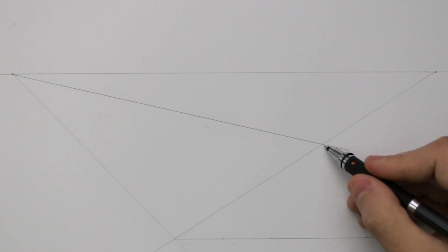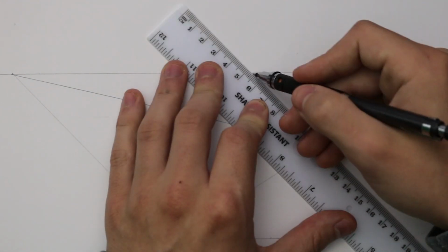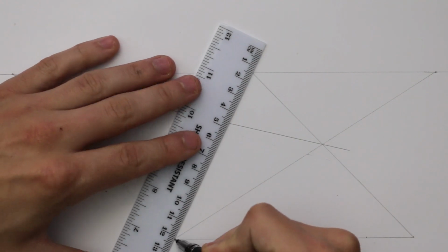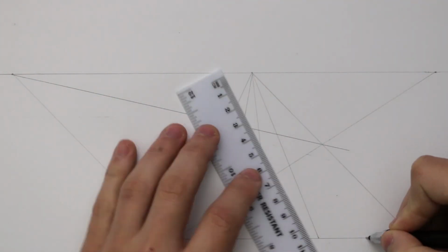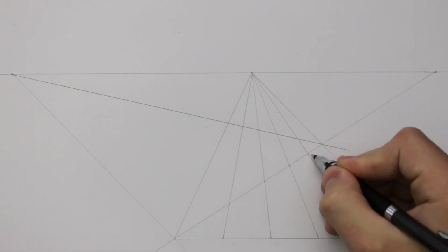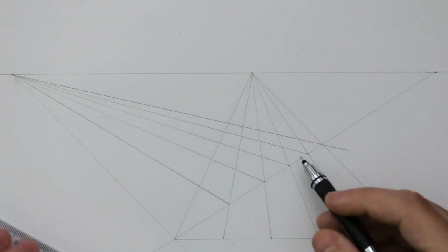And now I'm going to bring a line from the end of this parallel one which we just created to the other corner of the grid and extend it until it meets the horizon line, and that will give us a point that we can then use to divide that side of the grid. I simply bring my lines from those dividing points through the grid to that new point. Now we have these new dividing points on the grid that are foreshortened accurately, and I can bring a line from them to the left vanishing point.